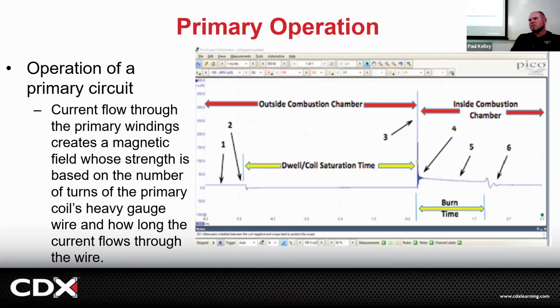And so that's mostly for next time, where we talk about actually taking these samples, which means we get the oscilloscope out, we probe into the primary side, and we set up the correct voltage range and time interval and take this reading. And this could tell us all about the ignition system. But you have to have a good overall understanding before you even know how to start to interpret this. So we will look at this one more time.